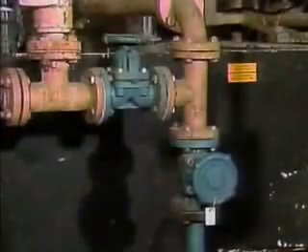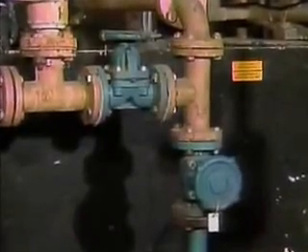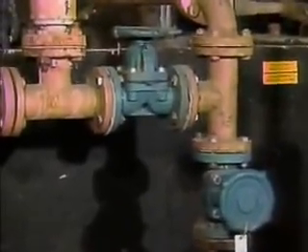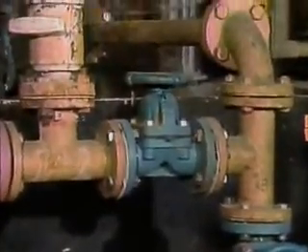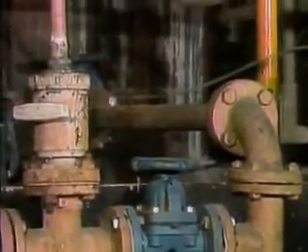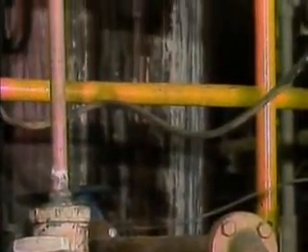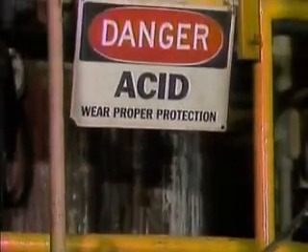When the hand wheel is turned in the open direction, the diaphragm moves upward, allowing fluid to flow through the valve. The diaphragm in a diaphragm valve isn't subject to uneven wear. So a diaphragm valve can be used both for throttling and for on-off service. The diaphragm also makes a tight seal that keeps fluid from contacting the operating parts of the valve. For that reason, diaphragm valves are commonly used in applications that involve corrosive materials and abrasive slurries.